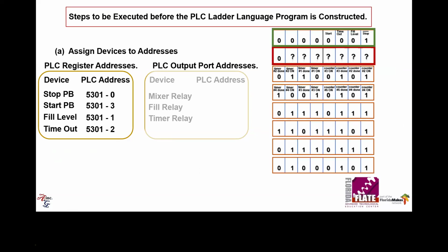All right, so what else is going on here? There is the bit address, but there's also the register address. And so now I've added the input register and the output register. I've highlighted them as green and red, put them on with all the rest of them. And there they are. This is register 5301 all the way down to 5307. All right, now it's time to make you think for a second. Please scribble it down so you know that you are not kidding yourself. What's the next register's address right here?